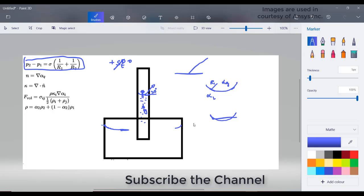In terms of knowing R1 and R2, here is some terminology that Ansys Fluent generally uses. This N is a normal. That normal is defined using the gradient of alpha q, where alpha q is the volume fraction. If you take the curvature, one side would be gas and the other side liquid. If you take air and water, alpha L is for water. Along the gradient, alpha L will have some value, maybe 1 here and 0.9 here, and if you go up to this point it would be 0. This gradient gives the normal direction, right?